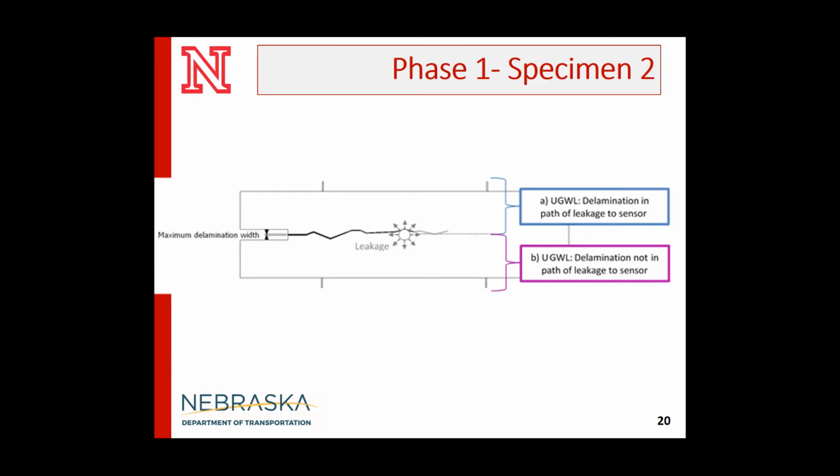So if you can really fine tune this, you might go as far as understanding whether your delamination is at the top of your rebar or at the bottom of your rebar, because there will be a change in how the data reacts to it, whether it increases or decreases.